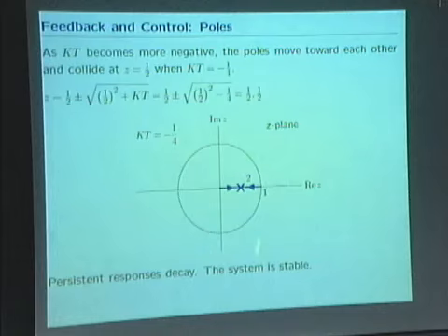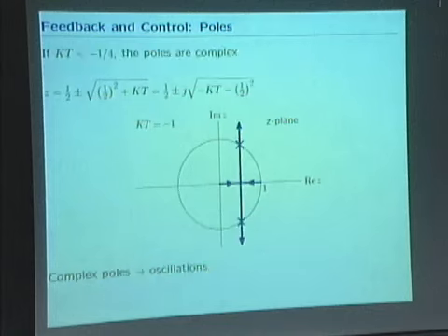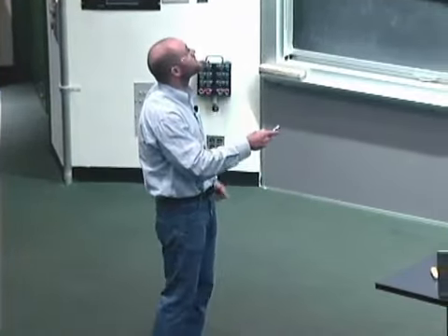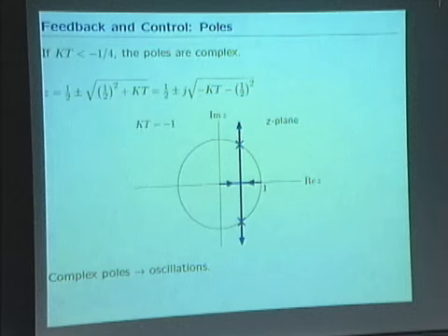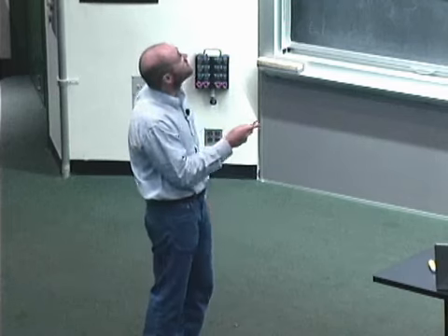Okay? And so here you've got a purely real response dominated by these poles at a half. System's stable. If you keep changing k, though, the poles came together and then they split off and start going this way. Okay? And in fact, if you look at -1, which was the one that was the best response that put a pole exactly at 0 for the system with no delay, okay?